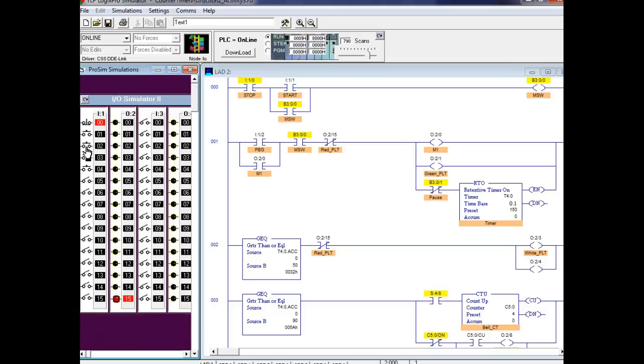By the way, we need to understand what we mean by inputs and outputs. Y'all know your timers are what type of instruction? They're output instructions. Contacts are inputs. Compares are input instructions, on the left-hand side. Your timers, move instructions, and math instructions are all output instructions. So output instructions go where?